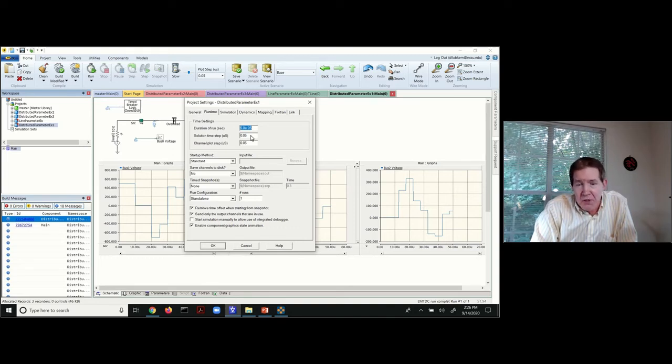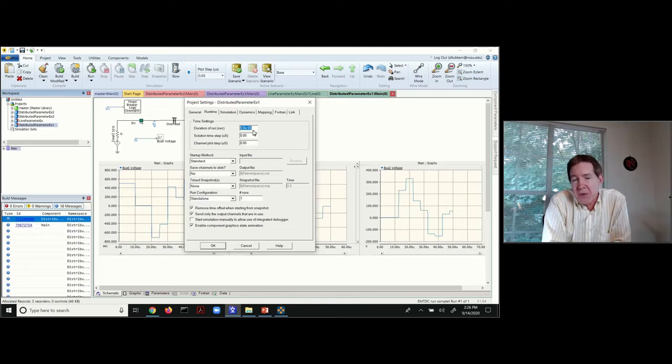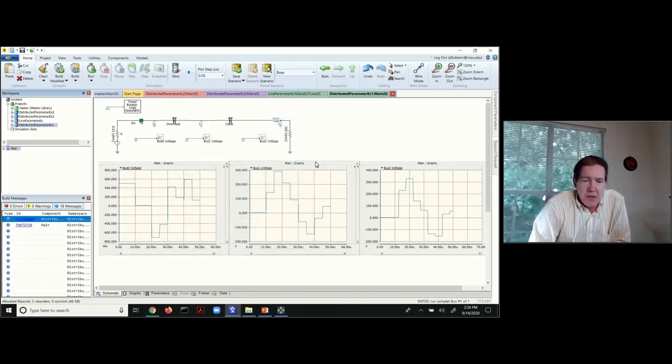So really small time step and small plotting steps as well. What this means is you're not going to run this study for a long period of time. This is something you're going to be doing in terms of probably tens of microseconds in some situations. And again, what we're really interested in is the initial transitions which occur.